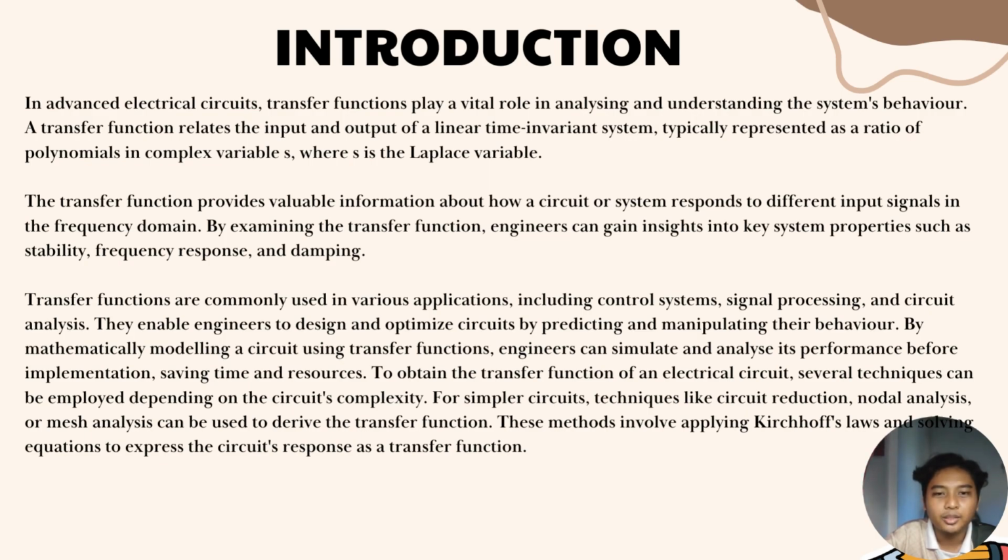resources. To obtain the transfer function of an electrical circuit, several techniques can be employed depending on the circuit's complexity. For simpler circuits, techniques like circuit reduction, nodal analysis, or mesh analysis can be used to derive the transfer function. This method involves applying Kirchhoff's law and solving equations to express the circuit response as a transfer function.